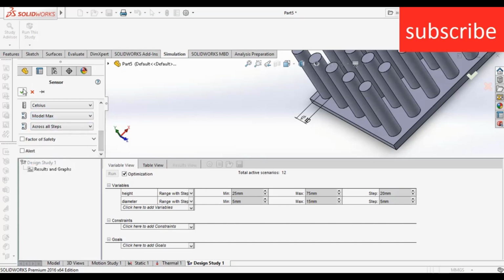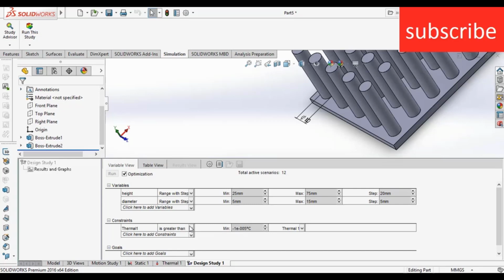Now click OK. Here it is asking what the constraint is. So my minimum constraint is that the minimum temperature should be 25 degrees Celsius. It should not be below 25 degrees Celsius. For example, I give you 100 rupees. Now what is the maximum amount you can spend? You will say 100 rupees. Why 100 rupees? Because that is your constraint. It is the limit that you set so that it doesn't go above that. So here the constraint is that my minimum temperature is 25 degrees Celsius, but I allow it to get above 25 degrees Celsius. So that is what a constraint is.